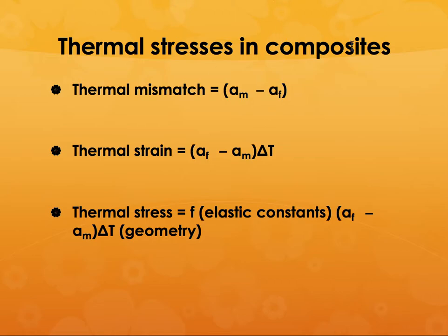So you can actually calculate the thermal stresses. There is a thermal mismatch, alpha of the matrix minus alpha of the fiber, and so the thermal strain is this factor times the temperature difference. So thermal stress can be given as a function of the elastic constituents times this thermal strain times a factor for geometry.